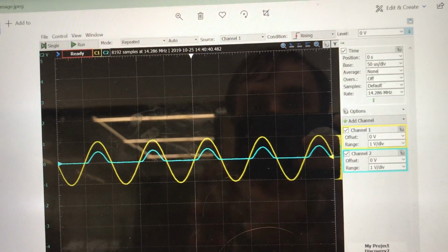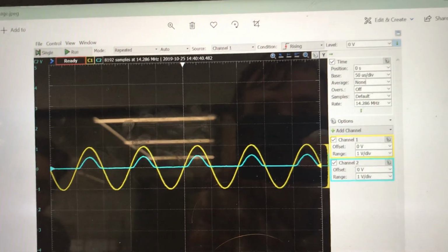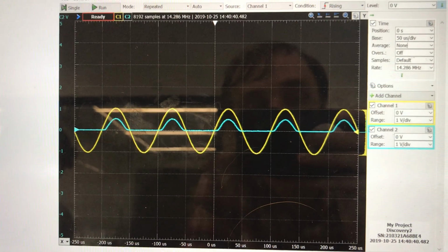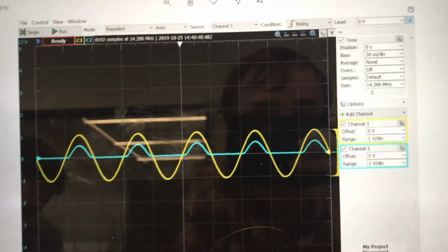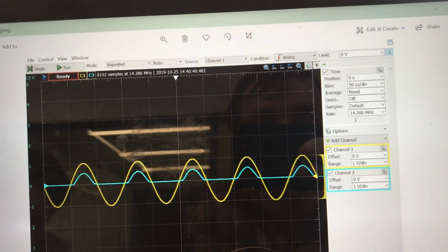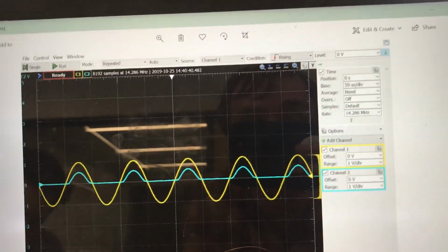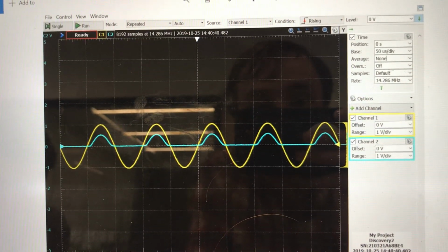We can do the same thing now with an input voltage of 2 volts peak to peak. Because of that, the voltage drop from input to output is much more pronounced, and the output is very low because the input voltage is pretty low. Remember, we have to get to a certain threshold voltage to even have an output at all. And this is without the capacitor.